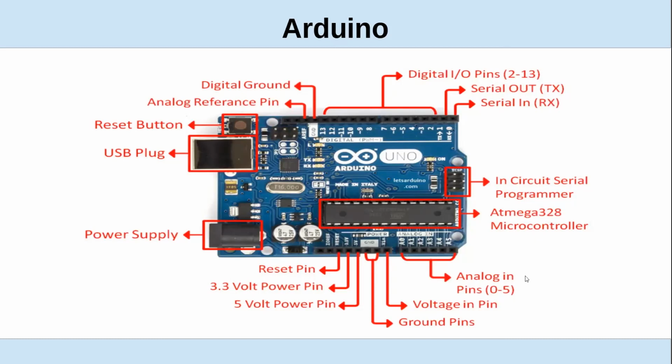This has 6 analog inputs, so they go to A to D converters. Some other things like you can connect it to USB. Here's your analog reference for the A to D converters. Because when you build those A to D converters, they will actually have comparators internal to them. So that's what the reference is for.